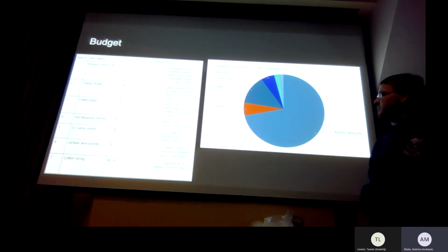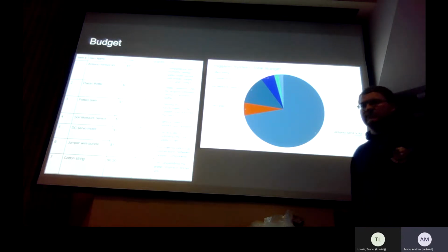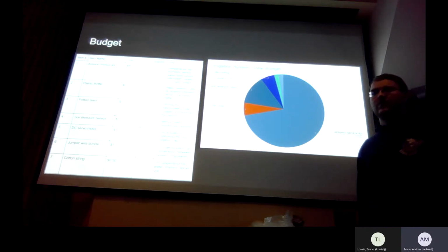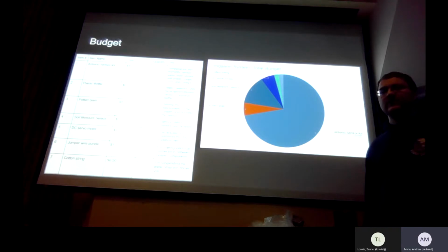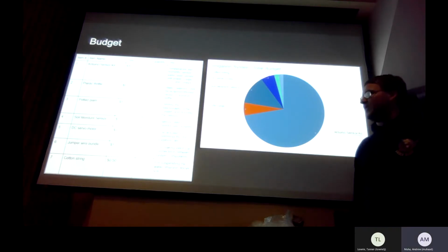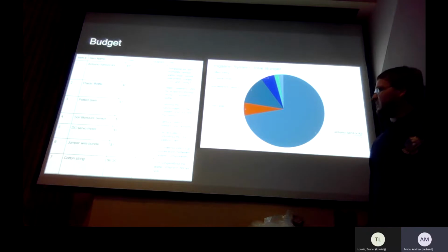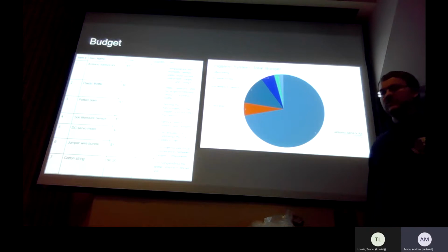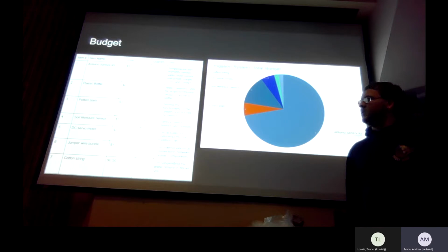Then we need a soil moisture sensor, which does not come in the Arduino sensor kit. This sensor will be used to monitor the moisture of the soil to make sure that it will be able to tell the watering system when it can apply the water from the plastic bottle to the plant. We'll need the DC servo motor, which is the actuator that will control the drip irrigation rate. It will receive its signals from the soil moisture sensor to use the plastic bottle to drip the water into the soil.